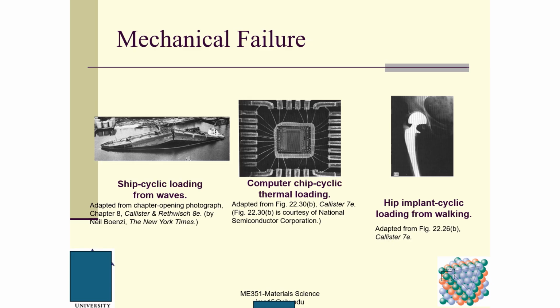So this is expansion, this is shrinkage, and this is cyclic loading in response to thermal changes. This is called thermal cyclic loading. This thermal cyclic loading can also result in catastrophic failure, meaning sometimes the chips break suddenly and unexpectedly. This is the second scenario.